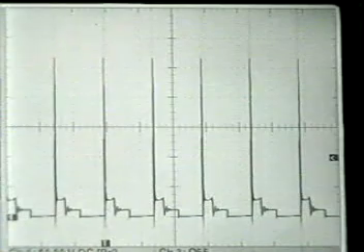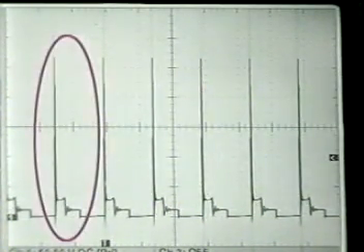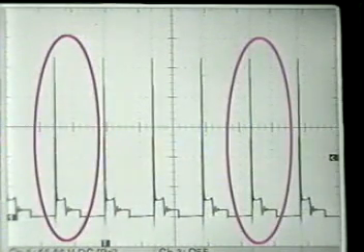So what we're going to do is backprobe primary, and you'll be looking at a primary waveform on your scope screen. What you'll witness on this vehicle is a misfire, again, that randomly shifts from cylinder to cylinder. Let's go ahead and look at this misfire, and watch very carefully, because you will see the misfire does not affect just one particular cylinder. It'll shift across that scope screen. You see it here, and you see it here.